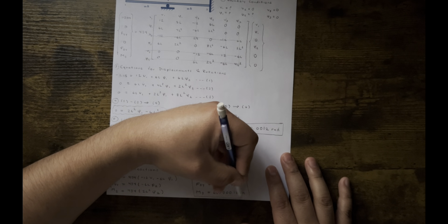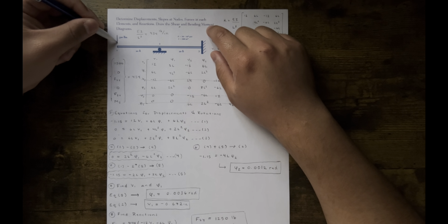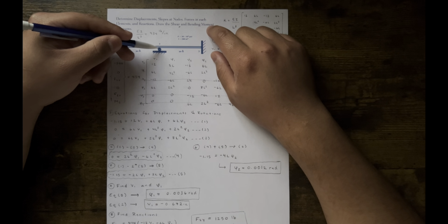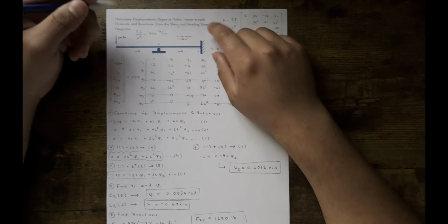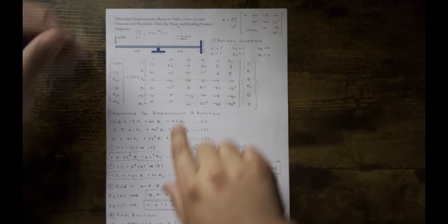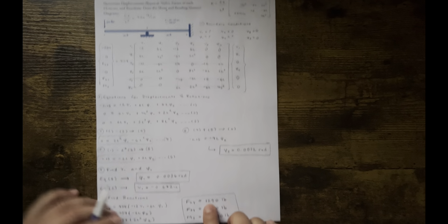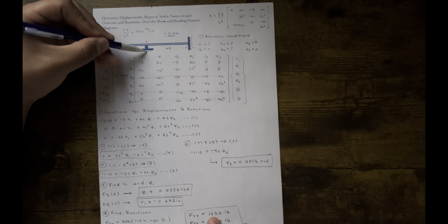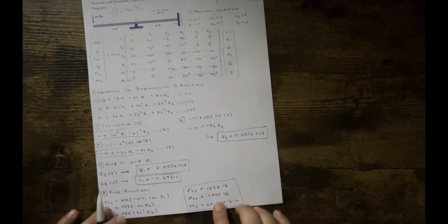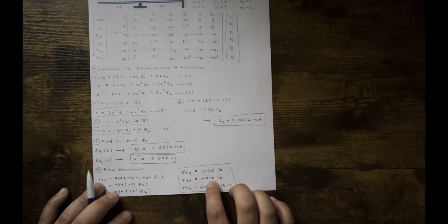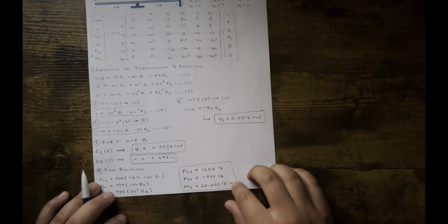numbers, and it's real easy to verify them. You just do statics, right? Easy way to verify this is 500 pounds going down, so that means the 2 forces here going up have to net 500 pounds going up, if that makes sense. So let's go ahead and see if that's true. At F2y, you have 1250 going up, right? 500 coming down, that means this one must be coming down at 750. So these answers make sense on the F2y, F3y. And usually when these two make sense, that means this one's gonna make sense.